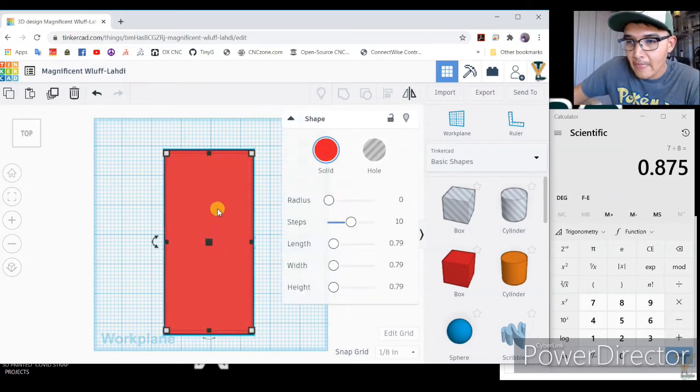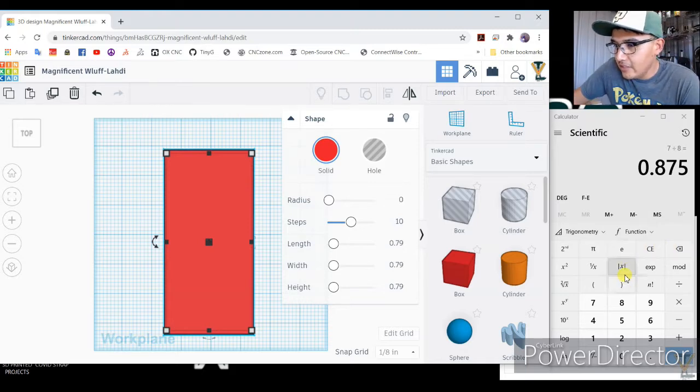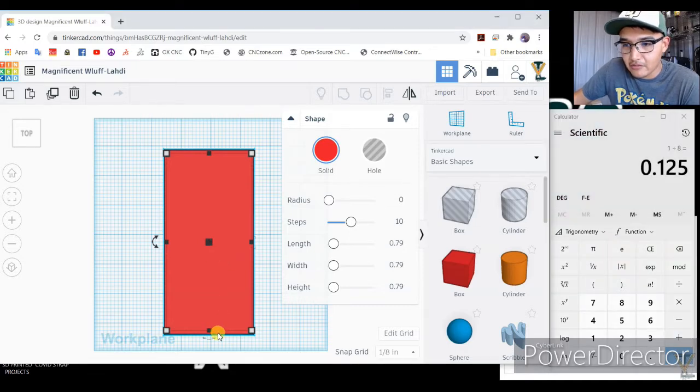your case. So we are going to increase it by, let's just give it a number. Let's just give it 1/16 of an inch clearance around your cavity. So 1/16 of an inch, two sides, that's 1/8. So what's 1/8 in decimal points? So 1/8, you are going to change this to 0.1 divided by 8. I know that already, but I'll just show you. It's 0.125. So we're going to increase that in our measurements.